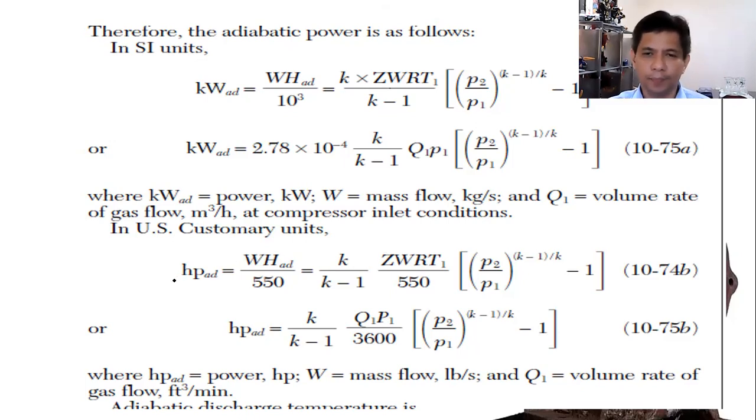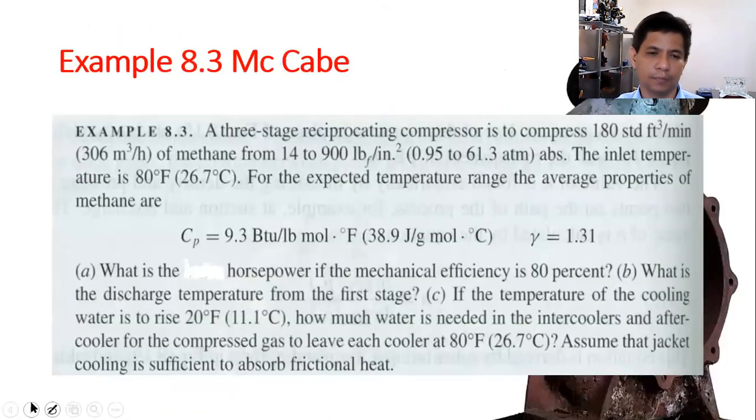But in my previous experiences, this generally gives the same answer as that equation. The one in the handbook and the one based on thermodynamics give the same answer. But the advantage of the delta H equals Cp delta T equation is that you can commit it to memory. It can become stock knowledge.